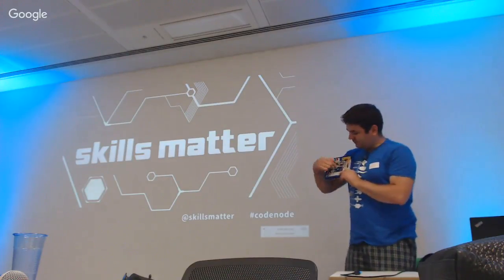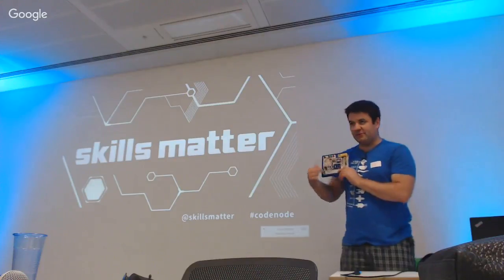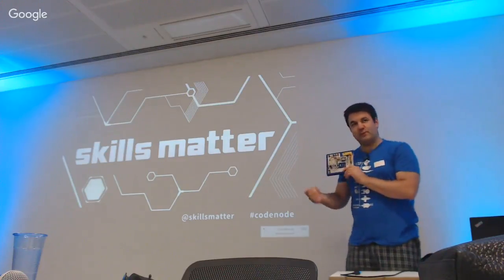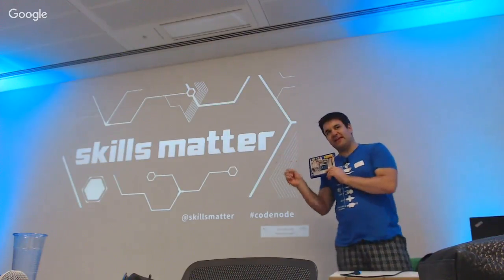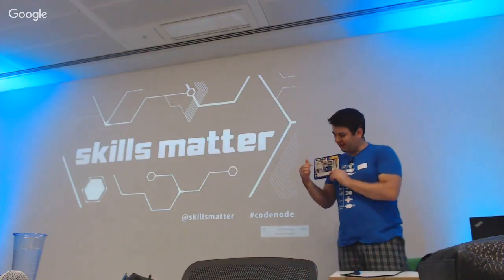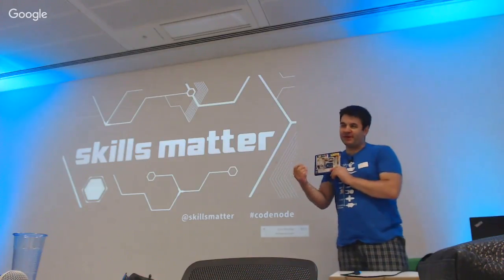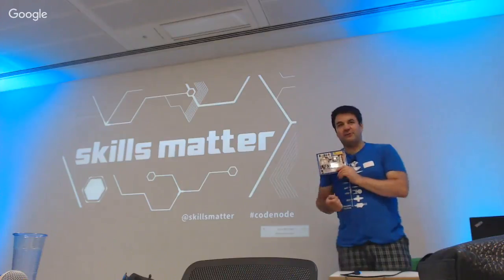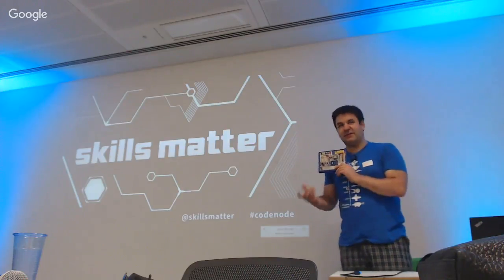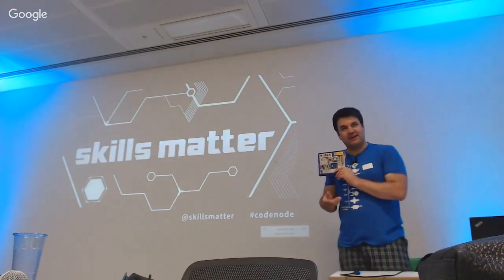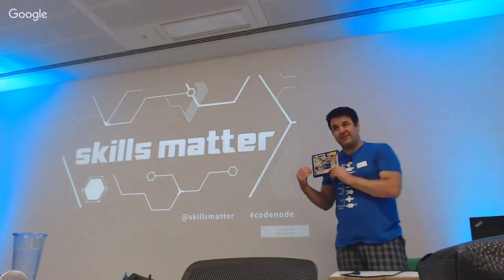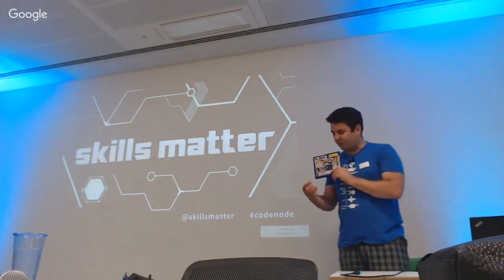And this is the RFID reader. What happens is the PIC chip wakes up once a second, flashes the LED of the team that currently owns this orb, and powers up the RFID reader and sees if a card's being presented. And if there isn't, it turns itself back off again and goes to sleep for another second. So that way I can run this off a battery for several days without it being a problem.